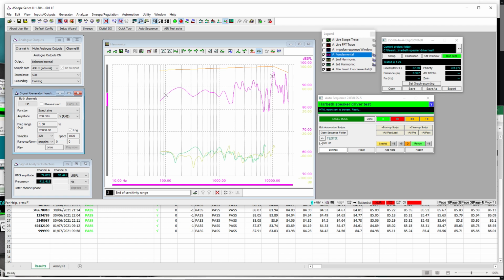And so you may also choose normalization, and you can do this at any frequency. So we can set, for example, normalization at 1K, so that in the resulting plot, the 1K point is always at 0 dB. And we're doing a relative plot, so all we're showing is the relative difference normalized at 1 kilohertz. So there's no need for shifting limit curves up and down or shifting traces up and down to see if they fit a limit profile. It's a very powerful technique.